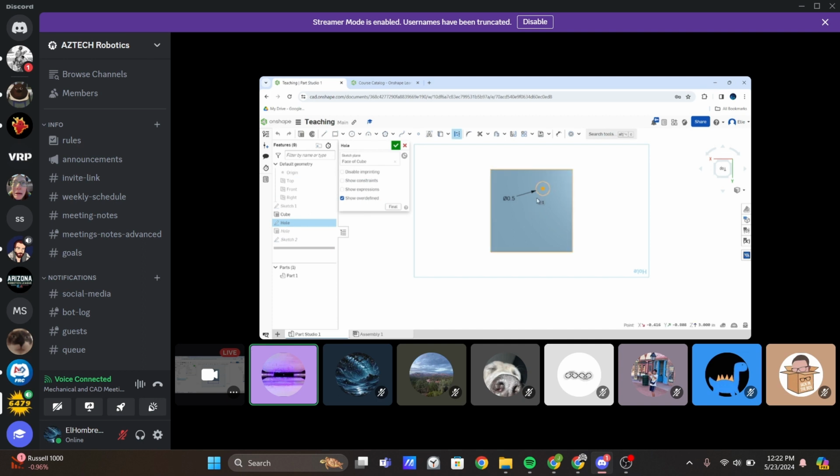So that is a very nice feature for aligning holes on brackets and gussets, because if you use it in one of the sketches, then it will basically automatically update and you won't have alignment issues later on.